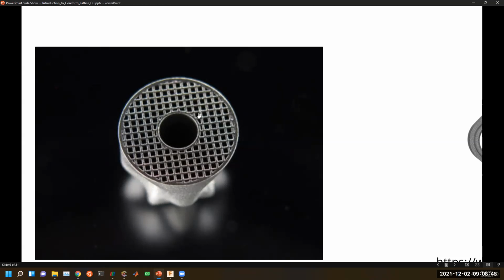But depending on what angle you were loading at, you'd get maybe a stiff response or then a soft response because you're at like a 45-degree shear angle. As well as you'd have some lattice structures or struts that might have been cut off or trimmed at a boundary. And you might not get the response you'd want at these locations.